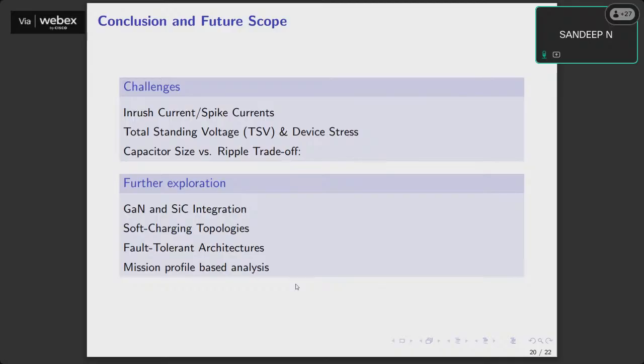Now, how to improve the lifetime of the inverter? The lifetime of the inverter is majorly decided by the thermal aspects of the inverter, right? Even though sometimes the design might say that a 1%, 2% lower efficiency is okay, thermally the inverter should be sound.